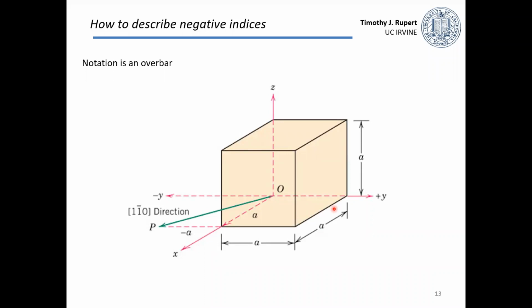One other detail to mention is it would get a little bit clunky to put negative signs if we had a movement in the negative direction. So in this example of this green arrow here, we're moving 1 unit cell in the X, -1 in the Y, we actually show that with what's called an over bar. So it's 1, 1 bar, 0. And that just helps us see that these are numbers that are separated from each other, not some sort of equation or mathematical operation.